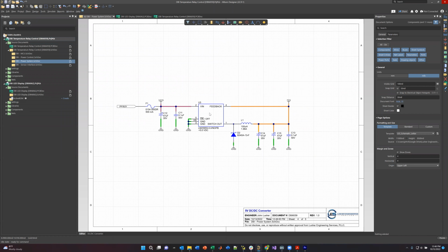Now I basically use the power port looking one with the little bar, and I label my parts 5V0 for 5.0 volts. It doesn't matter what you call it. I could call this VCC, whatever the name is, that's going to be the name of the net.